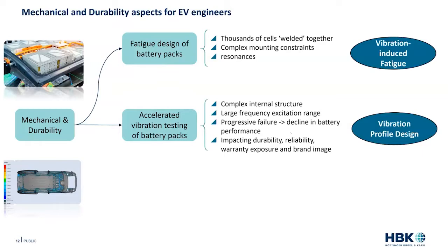And the idea here is basically to create a suitable load spectrum, a vibration spectrum that could be used in both the battery design that we just saw previously, and for the validation testing of the battery pack. So we'll see how to design a representative vibration profile.